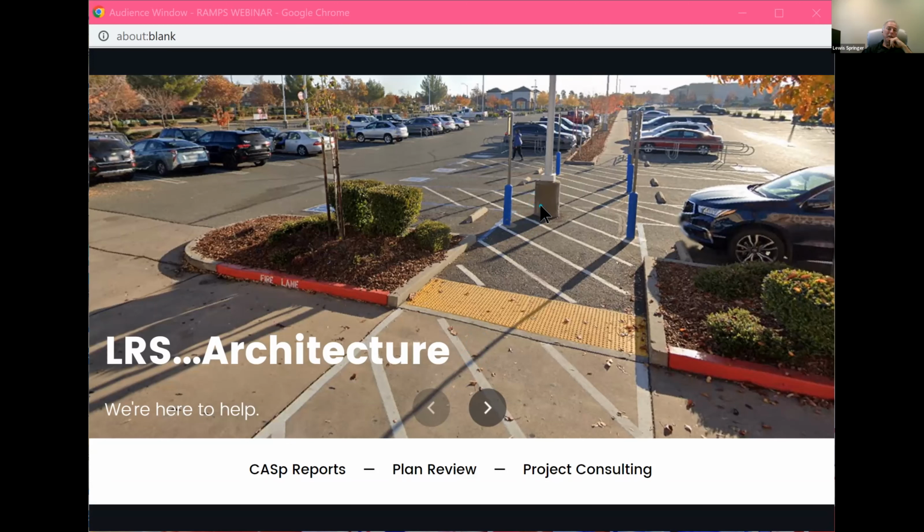Then when you're coming down this walkway and you come down a curb ramp, that would obviously require you to put detectable warning. But then at the curb ramp, you're actually in a safe pedestrian zone. So that's one of the things to start looking at when you have curb ramps that are really not curb ramps. And so the better solution here would have been, instead of a curb ramp, slope it down at 5%. So it's just a walkway and then come to a flatter walkway.